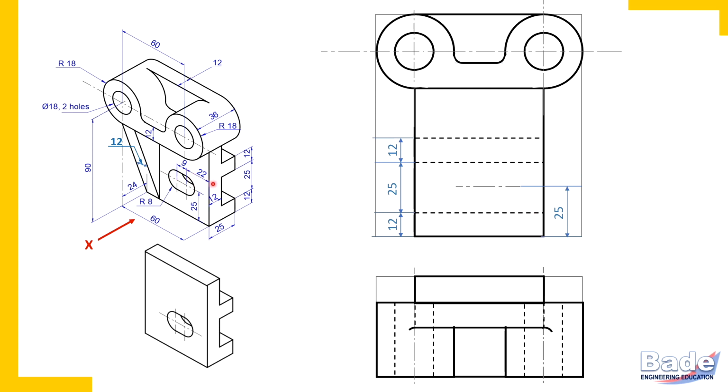Now watch this dimension, 22 mm parallel to length. So measure 22 mm parallel to length and draw the first center line here, which is vertical center line. And then at distance 9 mm, watch here, 9 mm, to be measured parallel to length again. One more center line.